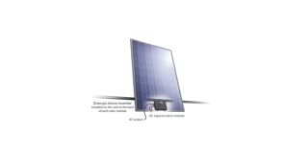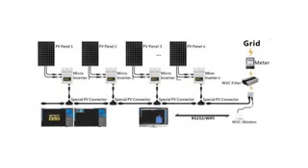The advantage is that if a single panel becomes shaded, then the output of the whole string of panels isn't affected. This is because each microinverter feeds into the grid independently. This would not be the case if one central inverter was being used. The disadvantage of microinverter is that the cost of electricity per watt increases.